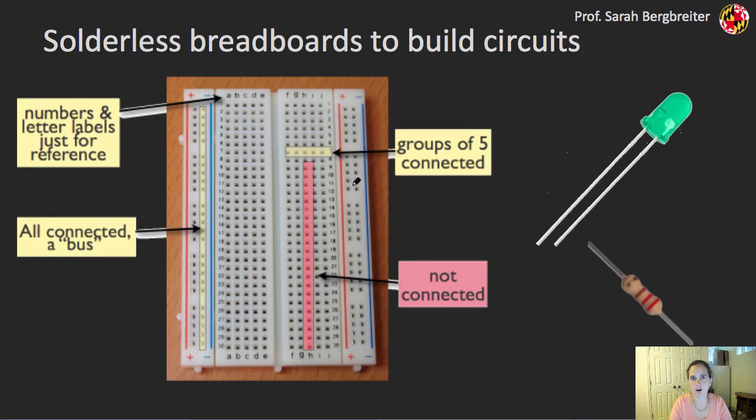And I can make that Arduino even more powerful if I connect it up to circuits that I build myself. And I might build those circuits on a solderless breadboard that you have in your parts kit. And so the way a breadboard works is typically I have these buses along the edges. So this huge thing along here, all of these pins are connected. And typically I'm going to make this line right here my ground.